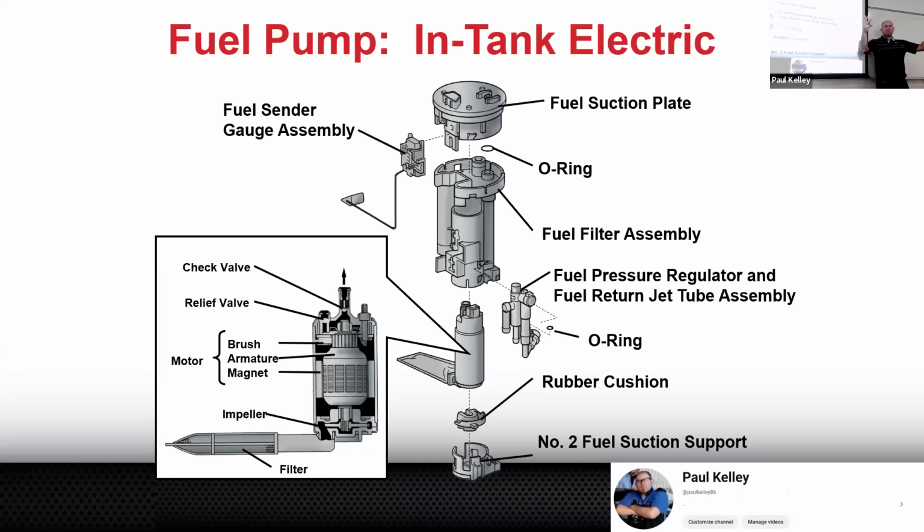Now, here's the good news. What I was saying about removing the fuel tank, a lot of times they'll put an access panel in the top. So if that fuel tank is under the back seat, sometimes you remove the back seat and there's an access panel. That one wouldn't be all that hard to diagnose the fuel level sensor. But sometimes they're hard and sometimes they're not. And sometimes there's an access panel and sometimes there's not. And if you ask my dad on his Blazer, if there's no access panel, there's about to be.